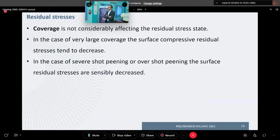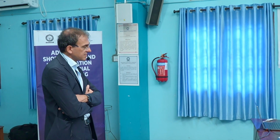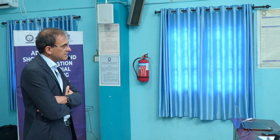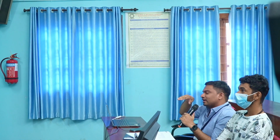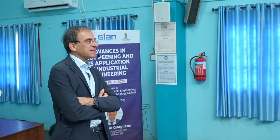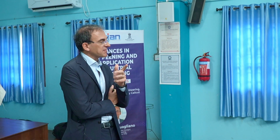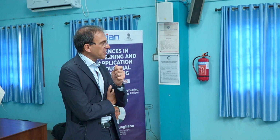Any question? Yeah. So from a fatigue point of view, which is more preferable? Should we get a larger compressive residual stress, or should the depth of the compressive residual stress be more? Indeed, we should consider that under fatigue loading, residual stresses tend to relax, and are partially lost.